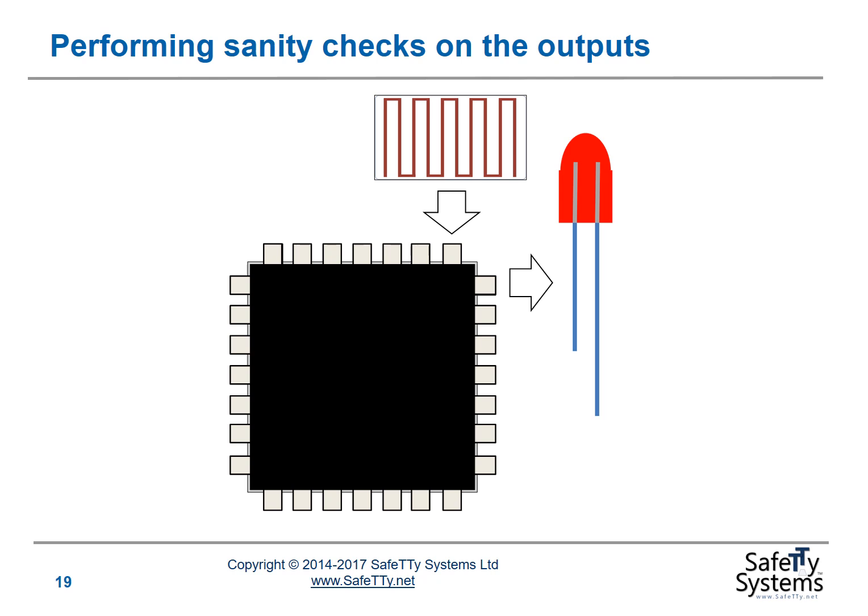However, if this wasn't a heartbeat LED but was part of the LED lighting system in a car, then we would expect to have some kind of sensors that would allow us to determine that, for example, the brake lights were not working correctly or that the indicator lights were not working correctly. Such checks would be sensible and would be useful, and we would expect to include them. So these are higher level tests that typically require additional hardware as well as additional software processing in the system, but they need to be considered in many designs.